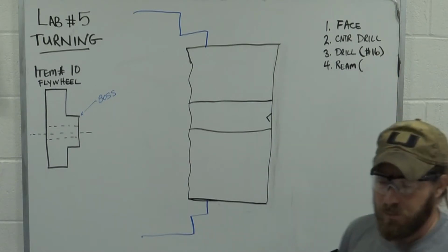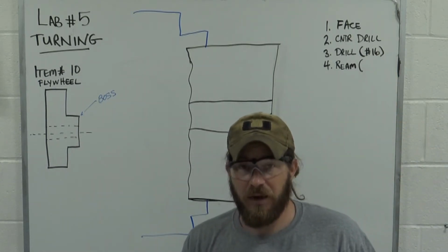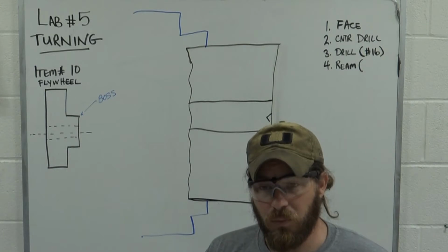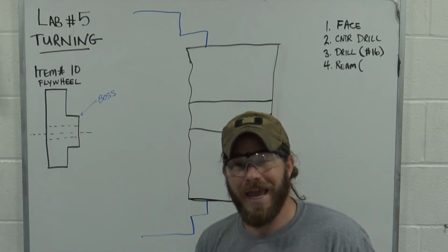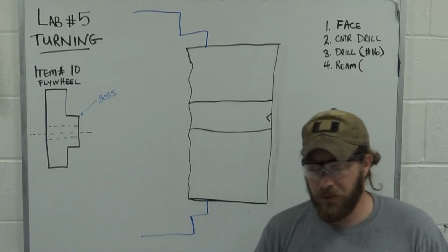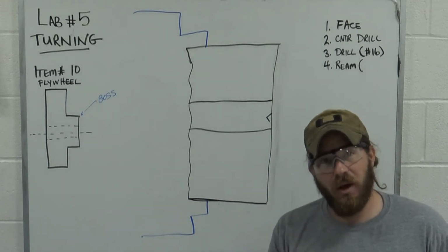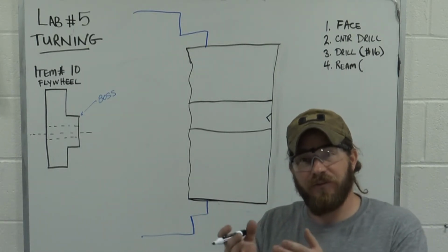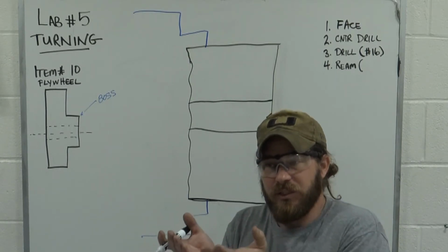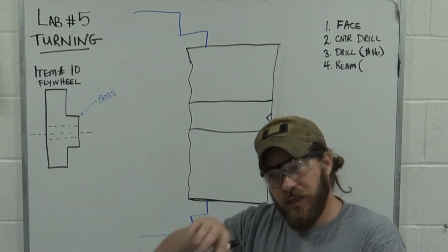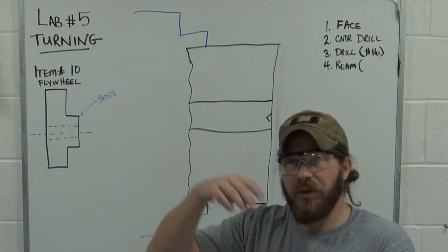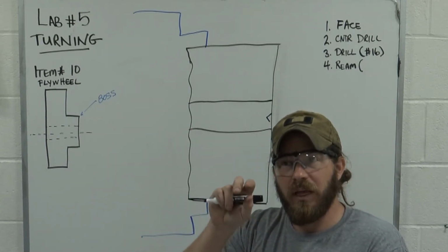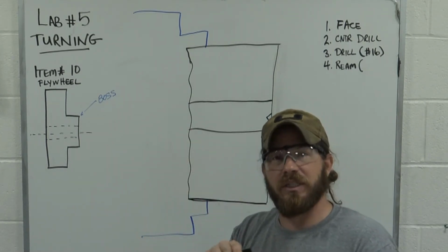And for this, we'll want to use the .1885 reamer. Again, that's the small end. That .1885 is the smallest my hole can get, right? If the reamer can do anything, it can make the hole slightly larger.